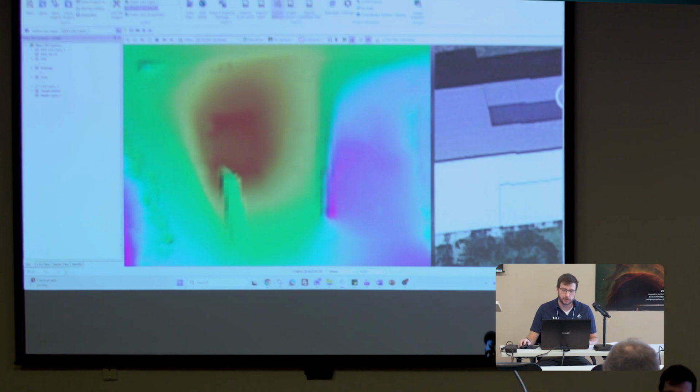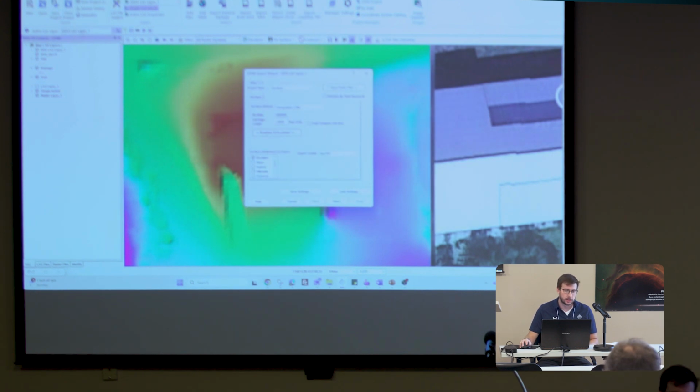So if we go to Export Wizard at the top, based on this, just set your active LAS layer to DEM to LAS. Based on this gridded LAS layer, we can make an ASCII XYZ export. A lot of people want that. A lot of clients ask, hey, I want to make an XYZ file based on my data, and I want it to be a thinned point cloud as well. And so this is a really good way to do that. Be surprised how many people ask for that.